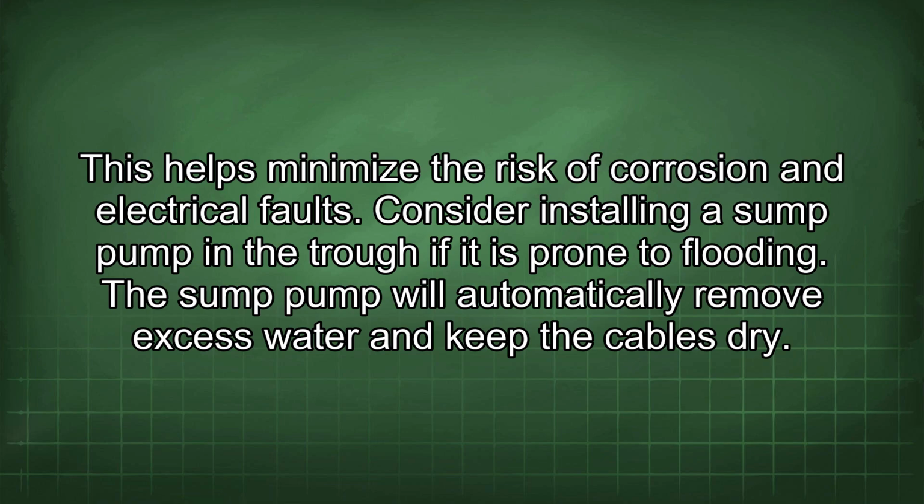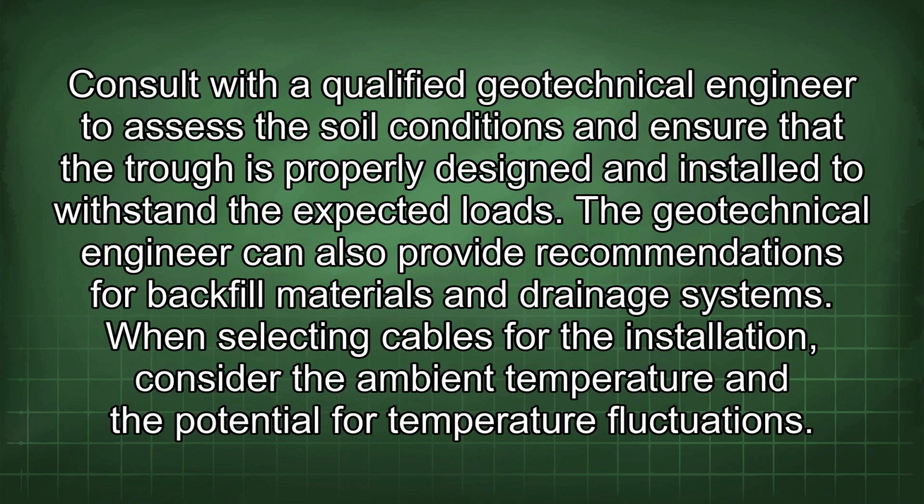Consider installing a sump pump in the trough if it is prone to flooding. The sump pump will automatically remove excess water and keep the cables dry. Consult with a qualified geotechnical engineer to assess the soil conditions and ensure that the trough is properly designed and installed to withstand the expected loads. The geotechnical engineer can also provide recommendations for backfill materials and drainage systems.